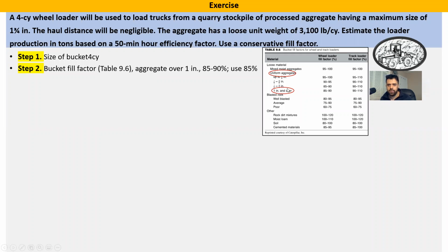Okay, so for this size of the aggregates and this class of materials, the load factor will range between 85 to 90% of the bucket volume.